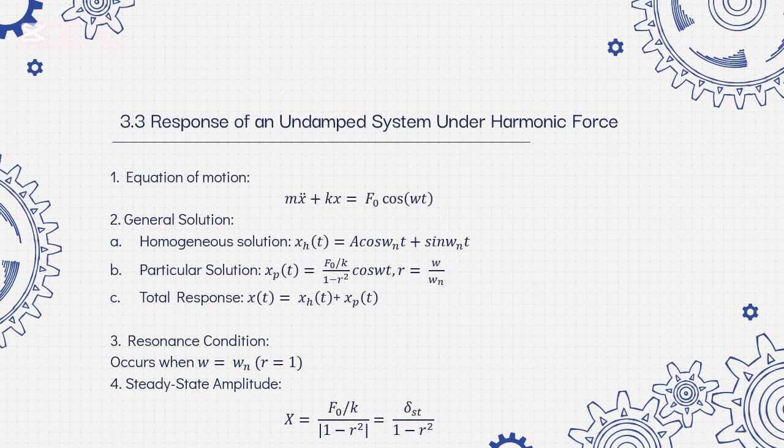And the steady state amplitude, which is denoted by capital X, depends on the frequency ratio, which is r. Notice as r goes to 1, X blows up. The third thing in this subtitle will be the resonance.